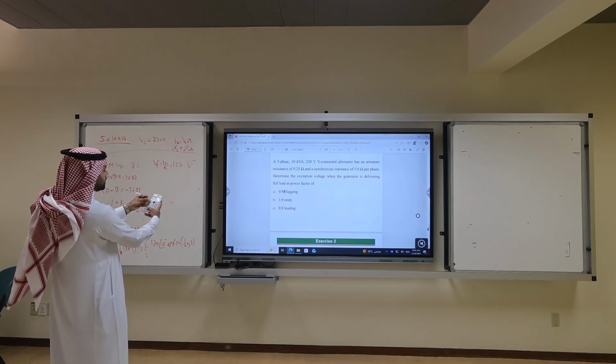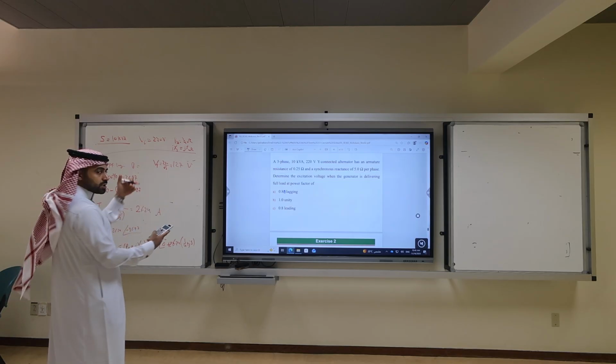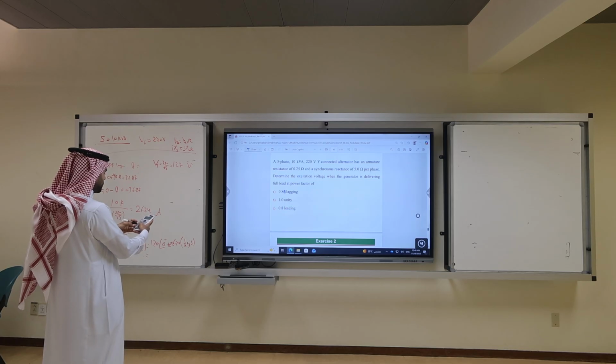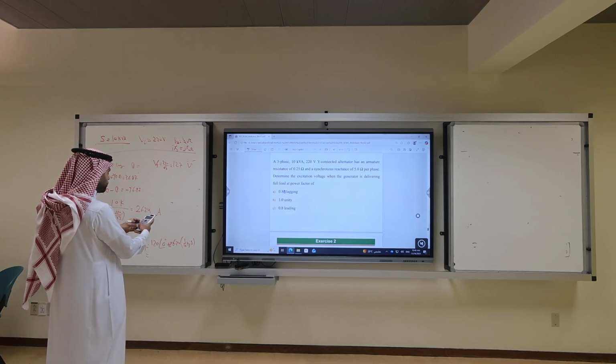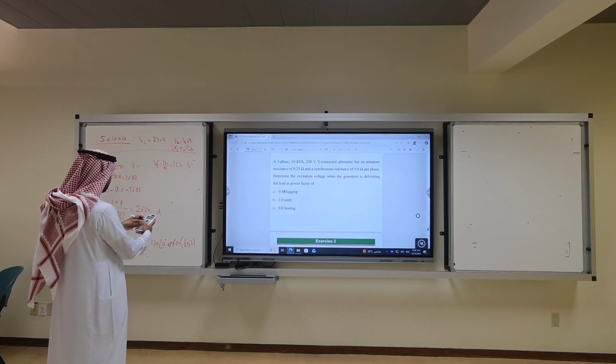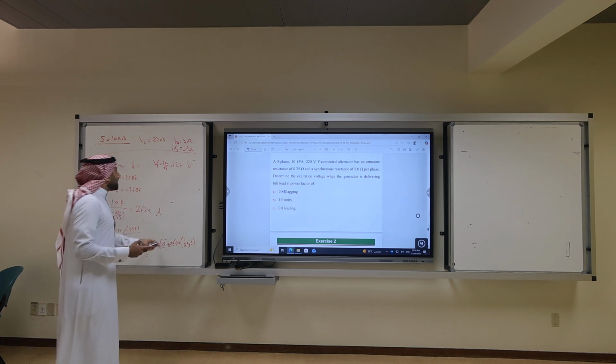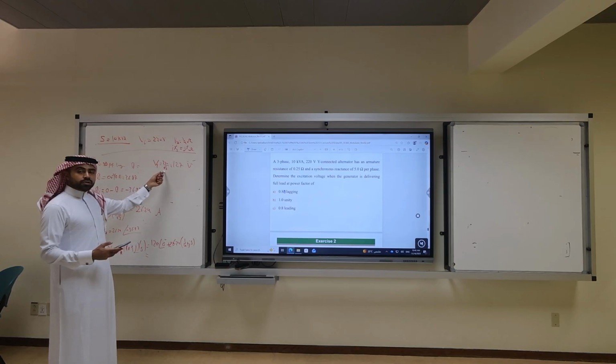So 120 angle 0, 120 because it's 220 over square root of 3, plus 26.24 angle minus 36.87 times 0.25 plus J times 5. It comes out 127, Doctor. 127 because this is 220 volt divided by square root of 3.